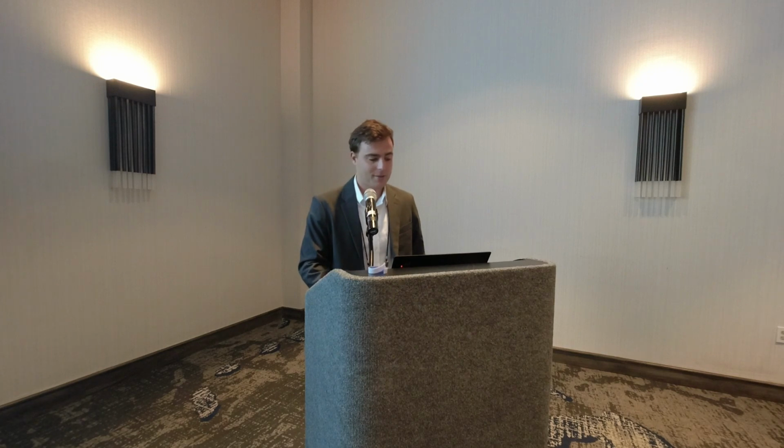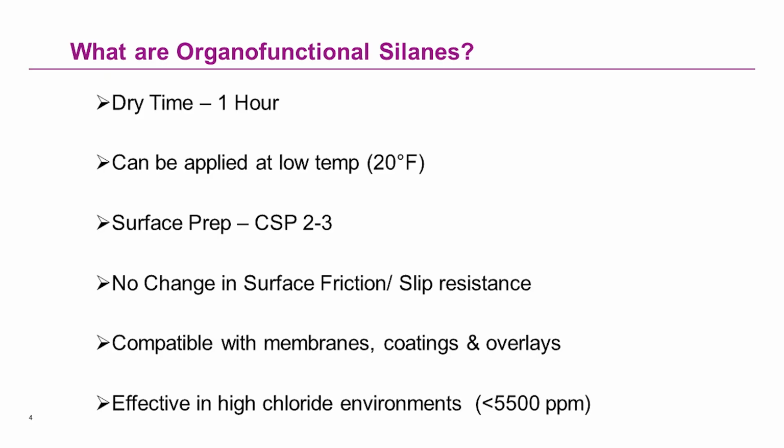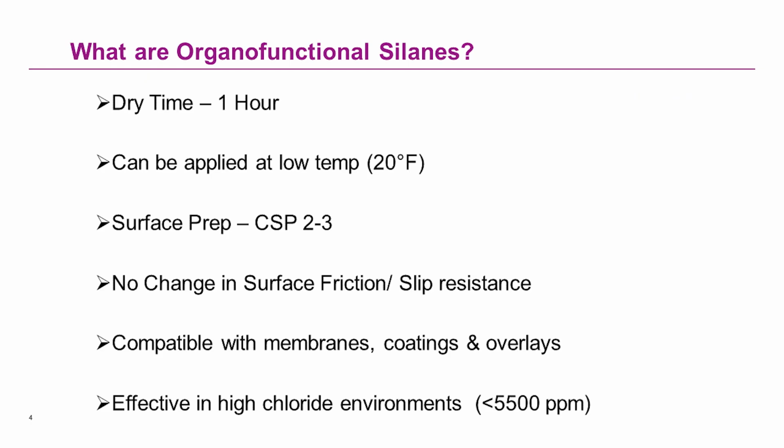Some other quick facts about silanes. Organofunctional silanes, especially ones with low molecular size, like a few manufacturers have, have quick dry times compared to some traditional silanes. For example, just to put our product out there, dry time of 1 hour, which means that you get to reopen your bridge deck a lot quicker. You have a lot less unhappy customers waiting behind the barricade to go on their bridge deck. Happier for everyone, it saves time and money for the DOT and the contractors. These are all 100% silane solutions, so there's no worry about water in them freezing, so they can be applied in low temperature conditions.